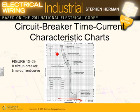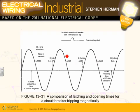You can see the faster the circuit breaker will trip, and that's called the time. You can see the curve here. This is your overload condition here. This is your short circuit condition, and in between is the melting or the opening of contacts for this time current characteristic curve. We'll look at this one in a second in a better view.